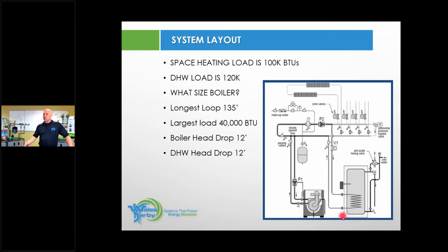So Jim told me that someone picked a 120,000 BTU boiler. So if I go to that universal hydronic formula and I have a 120,000 BTU boiler, Jim told you the shortcut. Move the comma over one position. That means I need 12 gallons of flow. 12 gallons of flow, with that circulator P1, also has to overcome 12 feet of head restriction.